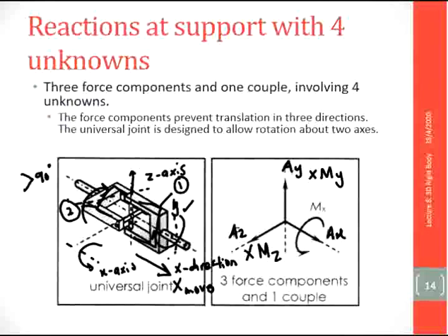It can move only with a small degree of rotation, less than 60 degrees, so it's not considered rotation. So this one has moment reaction. So there is Mx here. Okay.